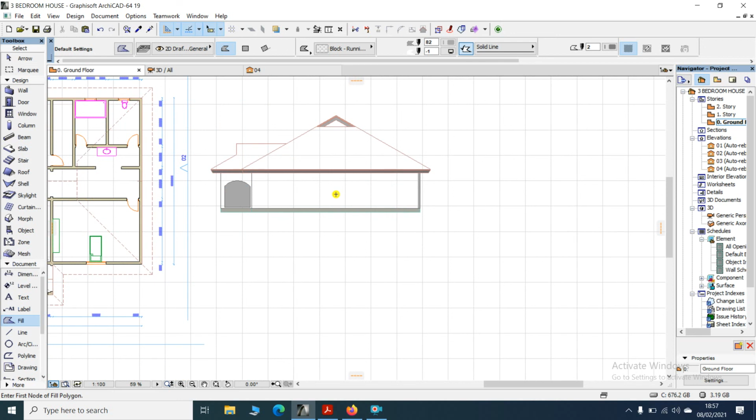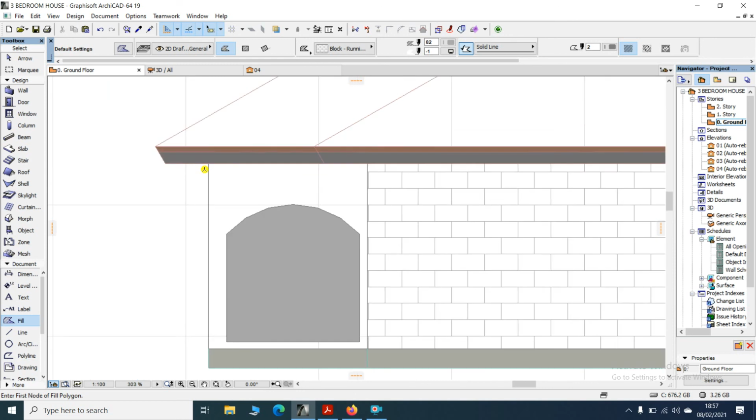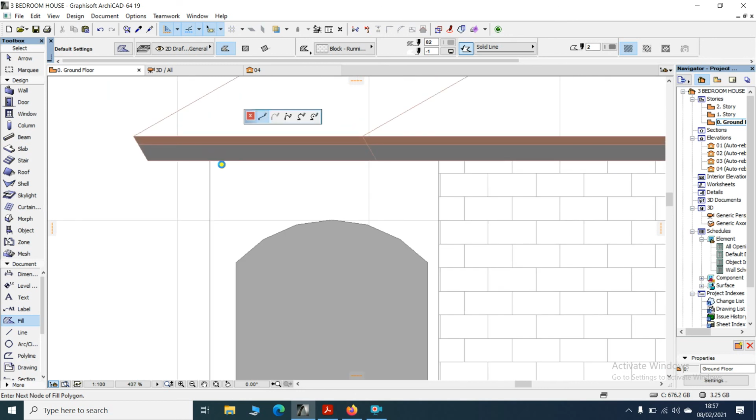And then you can come to where you want to place your brick running bond, block running bond. So I want to place it over here, and then you press the space bar, and then you left click, so it will come automatically. Also here I'll do the same, you press the space bar, so it is telling that region not found at this point. So you will come and select the polygonal method, and then you click at every corner.